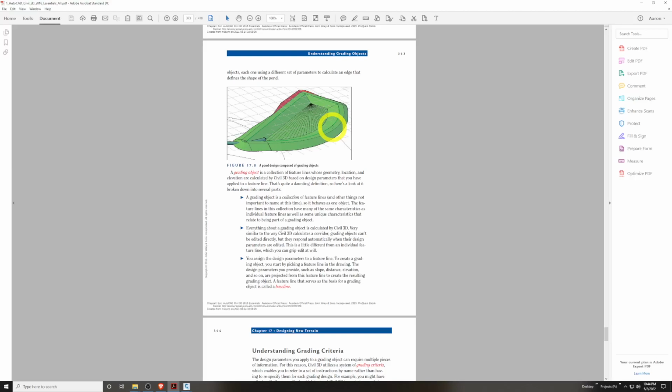So basically just ponds for stormwater drainage that are designed in different ways. They're like sumps to hold excess stormwater of a site. After post-land development, we have a lot of impervious surface. All this water needs to go somewhere. It can't drain into asphalt and concrete. So it generally promotes the development of these ponds and other drainage structures to retain for a while and release, or detain permanently in these ponds that were built by grading objects.